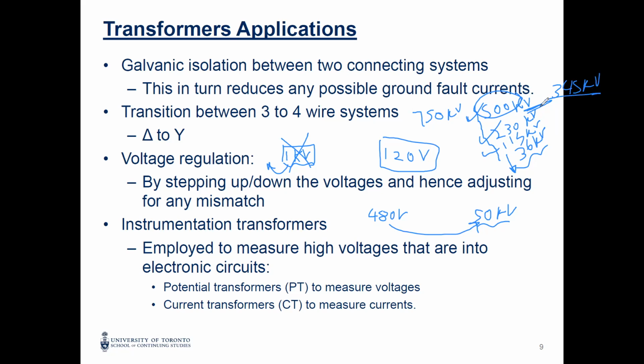So we have different voltage levels, and it depends on the system you are in, the standard in this system. And one thing is the geographical areas. You can go to very, very high voltage if you have a very long transmission system, because the larger the voltage you can go, the less voltage drop and losses, as we said. So I don't have a clear answer for it. It's a kind of gray, and it depends on the situation.